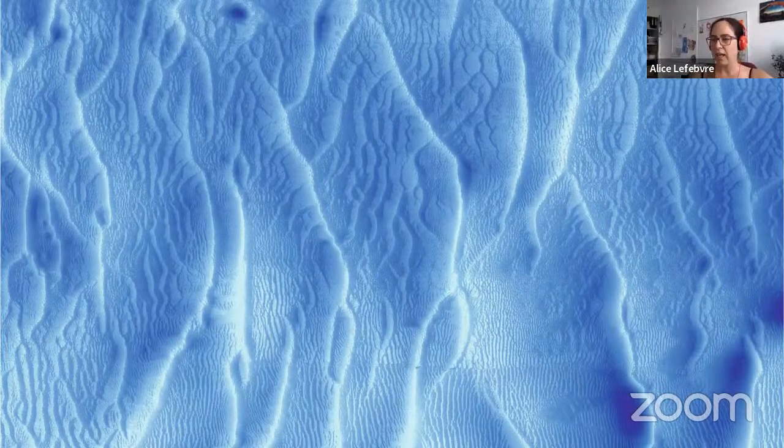I do numerical modeling of large-scale estuaries, and we have to parameterize the roughness. We're usually interested in whether we have ebb or flood dominant sediment transport, whether we have importing or exporting estuaries for sediment. So when I heard that these dunes change the roughness depending on whether we have ebb or flood flow, I was wondering if you think this will also have a large scale effect on the sediment transport directions, and if we have to incorporate this in our models to predict whether we have flood or ebb dominant sediment transport. Exactly. Do you know Gerald Herrling, maybe?